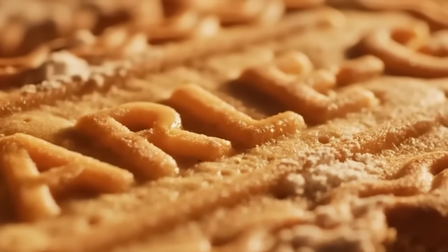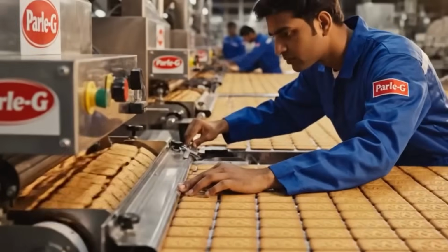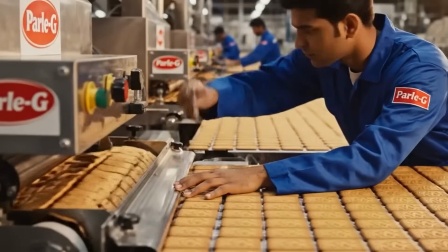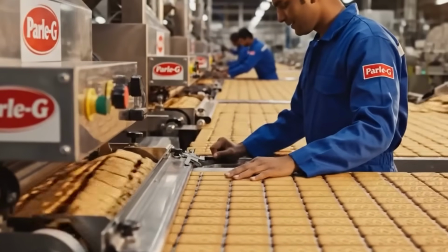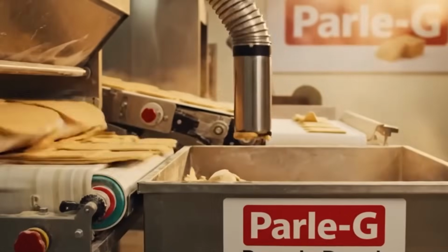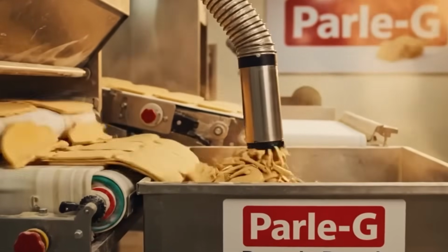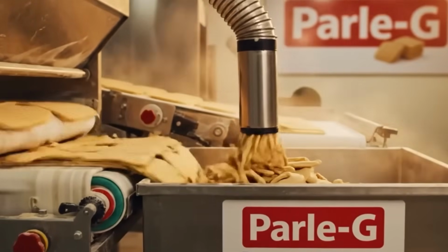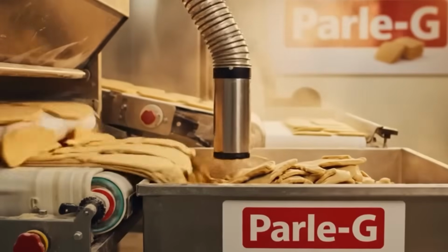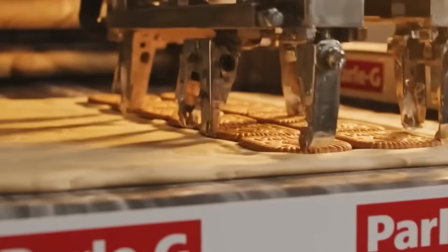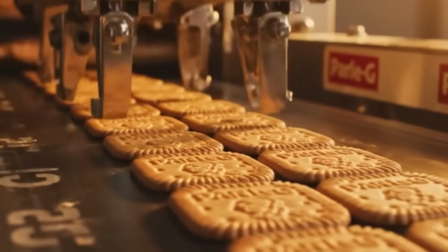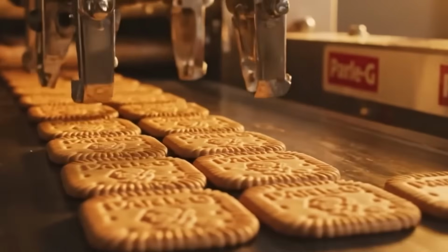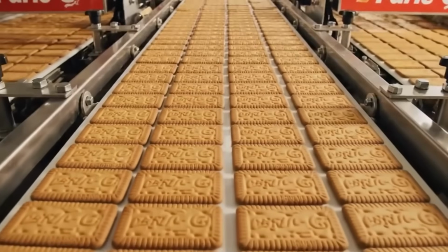Airflow influences drying and surface texture. Strong convection removes moisture fast and yields a drier surface. Gentler airflow allows more, even internal drying. Many ovens use independent top and bottom heat control. Bottom heat drives structure set from the band side. Top heat drives surface color. Balancing top and bottom heat prevents warping and ensures even bake.